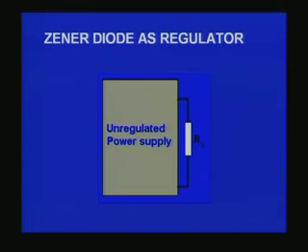So when I now connect the voltage source, which is an unregulated voltage source as we call it, to a load, for example RL, as you see on the screen, in principle we expect the voltage applied across the load resistance RL to be a constant, irrespective of what load resistor we connect. But because of the internal source resistance, you would find this voltage will not remain constant as we change the value of the load resistance.